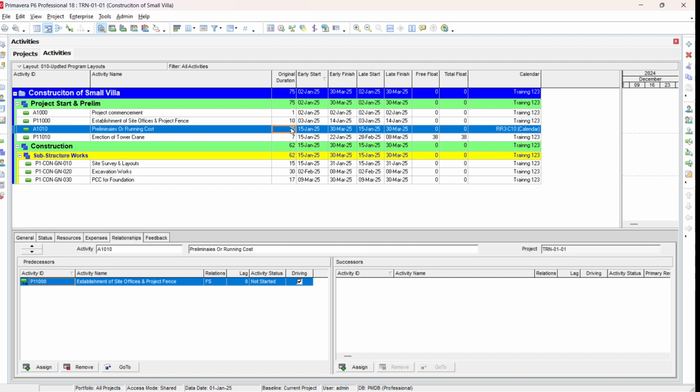Normally, the authorities which are controlling the construction have 5 working days, so they are not coming for any inspection or any check in the holidays. Similarly, the consultant engineer or supervision consultant have 5 working days. So if you submit any inspection or any submittal for approval, you have to consider that it will take 5 days.